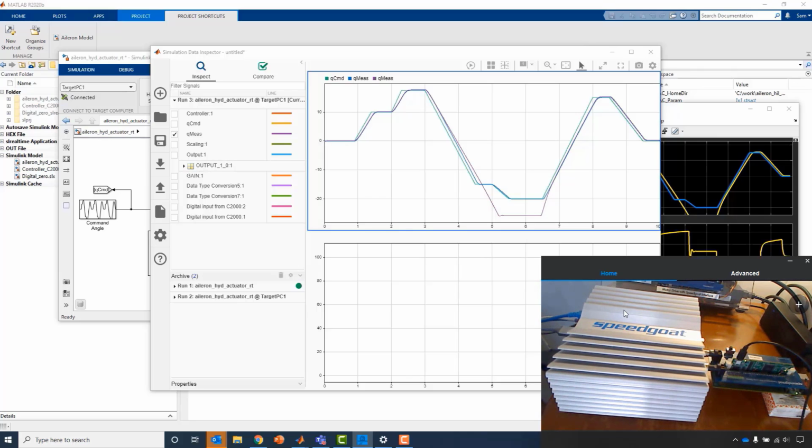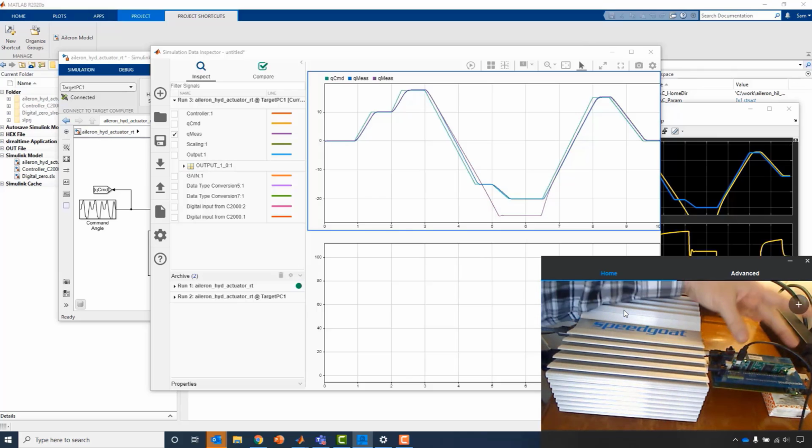When you run a hardware in the loop test, you're taking the actual deployed version of your controller, and instead of testing it with a real machine, which may not be available, may be very expensive to test with, or have limited availability, or maybe you want to test edge cases. And let's do lots of iterations in a lab before we start getting more real hardware involved.